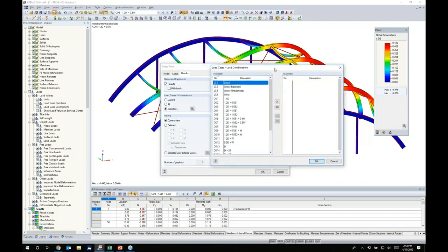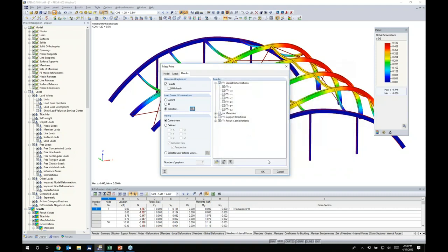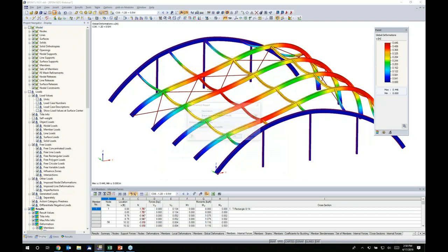and I actually can choose this option here where I can move multiple load combinations for consideration of these pictures. I'm going to choose all of my ASD load combinations here, and I move them over to the right side. I click OK. So now I click OK through these dialog boxes. The program creates these pictures and it says, well, wait a minute, you don't have a printout report quite yet. So do you want to create one now? And we can choose one of these printout report templates by default. And so we'll just choose this first one.